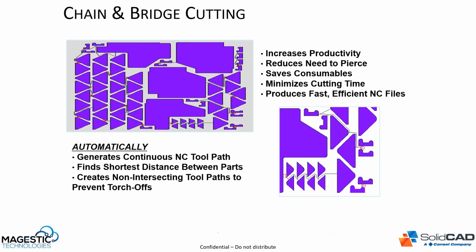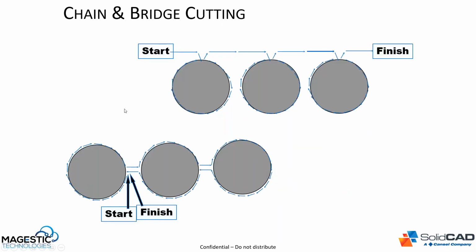And while this keeps the machine on, it also makes the material utilization less efficient. So we have to have the space in between parts in order to place these chains between parts in order to drive this optimization process. Depending on your constraints and your manufacturing concerns, chain and bridge cutting can be effective, but a lot of our customers end up using more of the minimum pierce logic as well. So it's a good example of chain cutting for this particular machine, and bridge cutting as well.